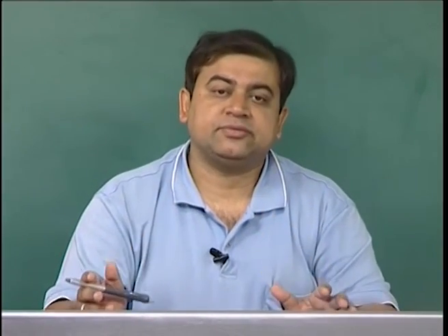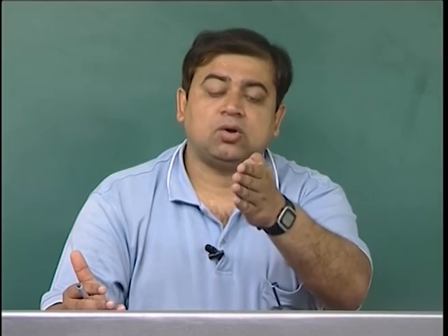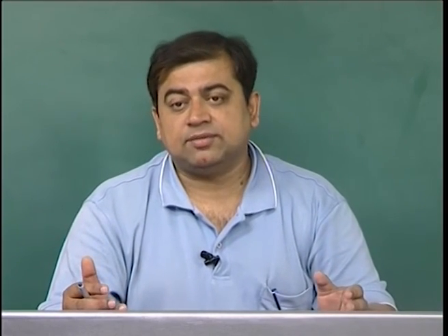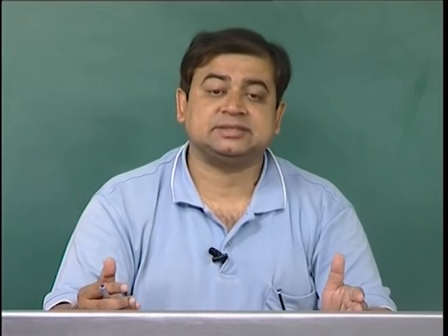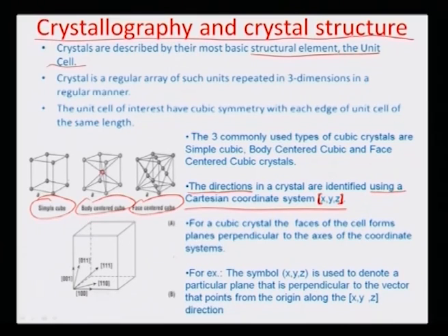And not only that, if the growth is along a certain plane, then it can be a [1 1 0], or let's say [1 0 1] or a [0 1 1], which corresponds to different planes of growth. And then there can be a very interesting growth along the [1 1 1] direction, which means that it is something like a triangle here, as you can see. So the [1 1 1] direction typically is perpendicular to this particular triangle. So the direction of growth is perpendicular to it.